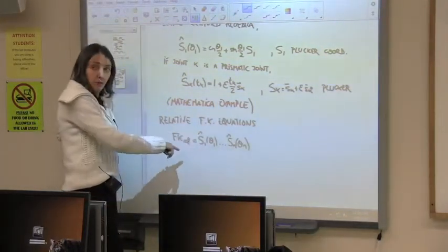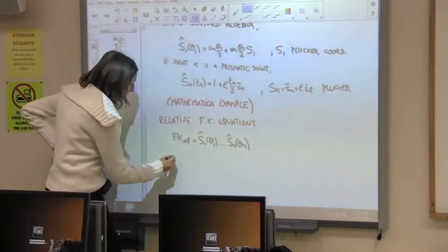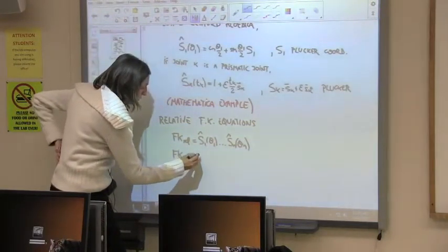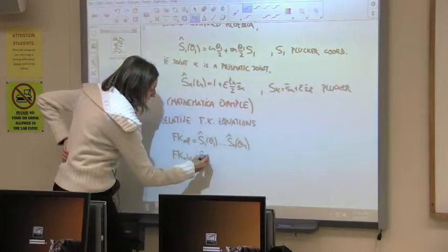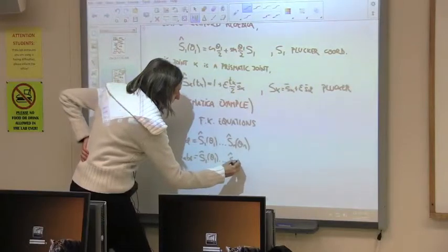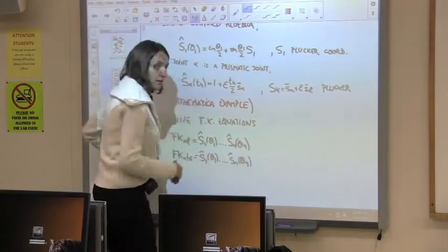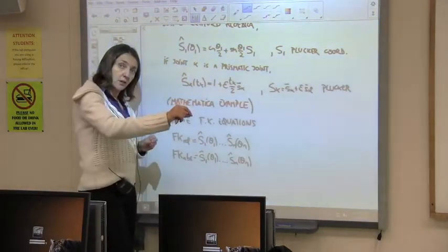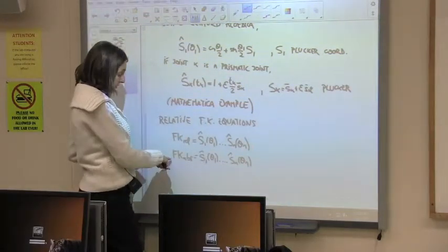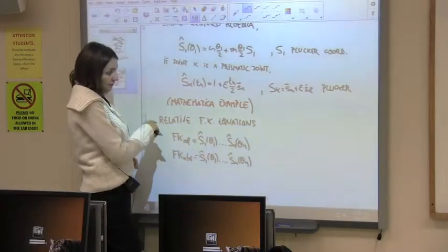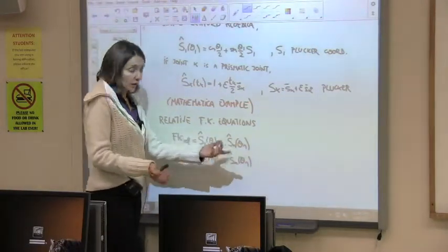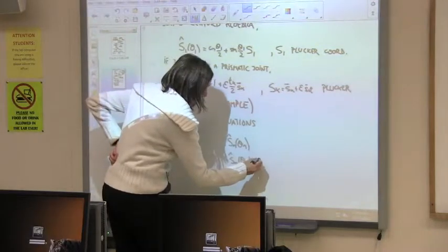You can recover the absolute forward kinematics very easily here, the one that we were doing before. You can use the same methodology. You can do the relative forward kinematics, and then just multiply times the displacement to the initial configuration, which we just did. If this is the 0i, which was D0 inverse, we just multiply times D0 here, and that's it, times g.